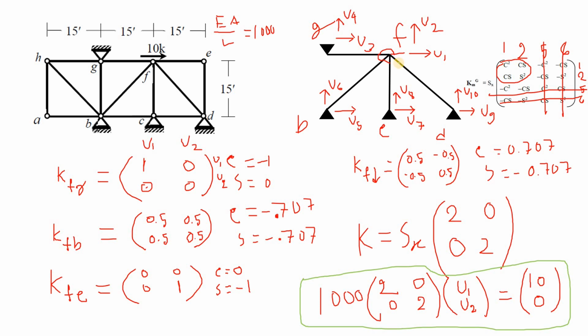So the reason for me doing that is, if I had considered the lower bearing angle, for example, if I had considered GF and then BF and then CF, in that case the F, the 1, 2 would have become the later part of the equation. That way we could not have developed such a simple equation to get the displacements, right?